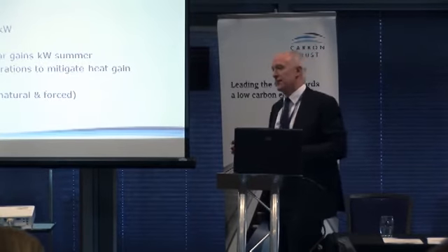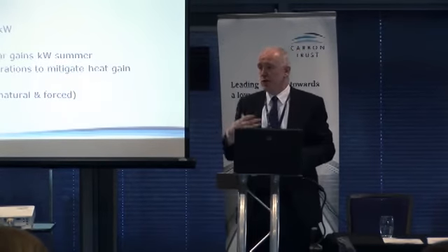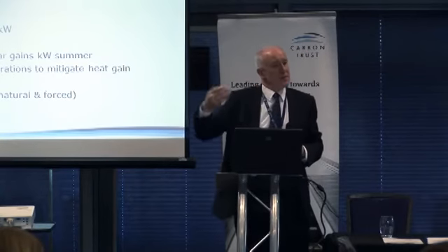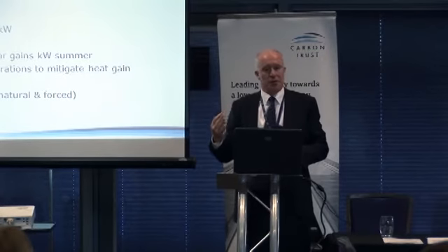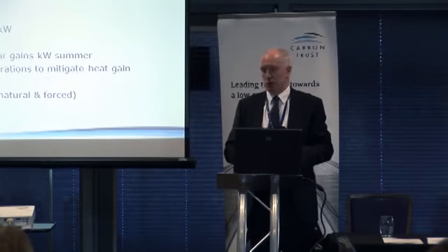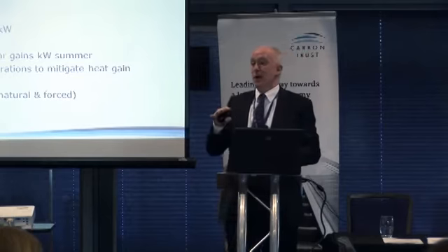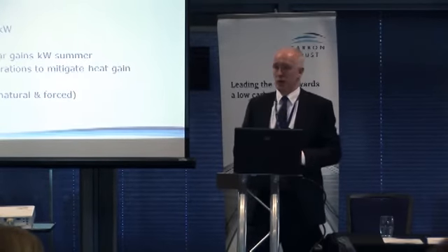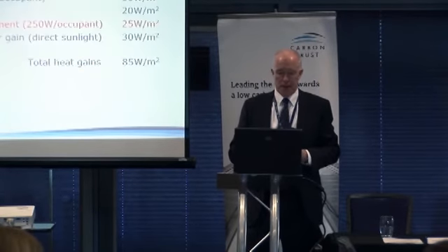Our heat gains come from the lighting, they come from the IT loads, they come from us. We each generate about 100 watts a person, so if we're in 10 meters squared of office, that's 10 watts per meter squared from ourselves. Solar gains through the windows are very significant. We need to cut that out, and we need to mitigate with controls the operation of all of our plant. And if we do that well, we can create a comfortable environment with natural or forced ventilation without air conditioning. That's got to be the solution within our buildings, and that's how we're increasingly designing our buildings.